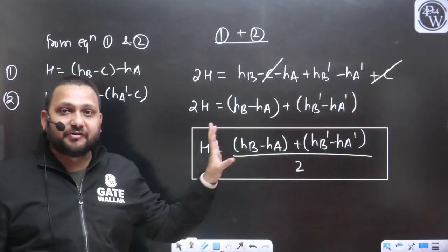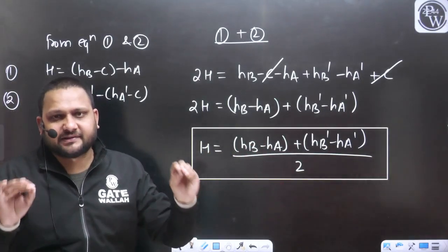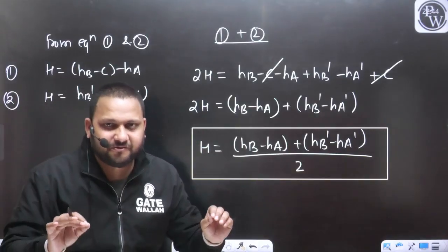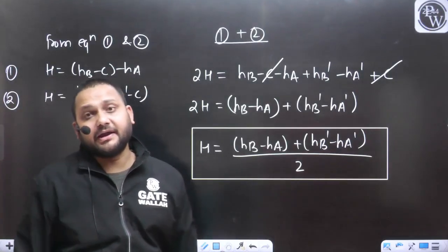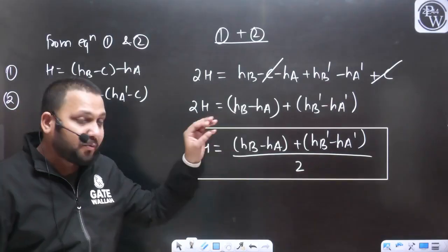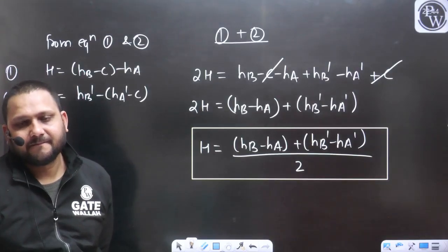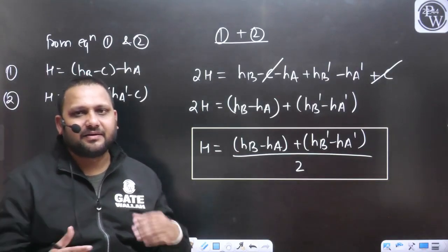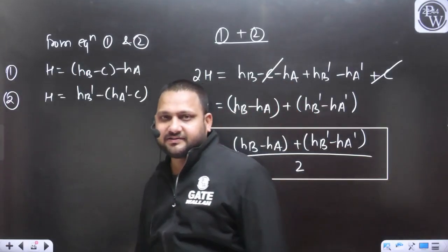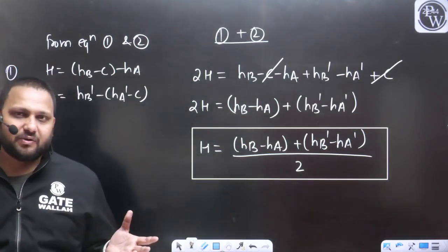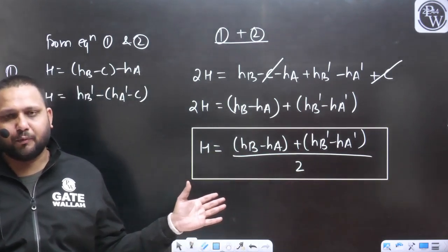No matter, with the help of the incorrect reading, without applying any correction for the curvature, for the refraction, ultimately you can calculate the elevation difference between the point A and B directly with the help of these incorrect readings also. So you need not apply the curvature correction, refraction correction for the reading. Then you will calculate the elevation difference. Directly you can calculate the elevation difference between the point A and B.